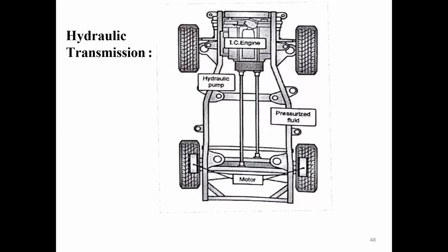The swash plate is tilted in forward direction. The pump pumps the oil in forward direction and the motor and wheel rotate in forward direction. The discharge of the pump and the speed of the vehicle are proportional to the angle of the swash plate.